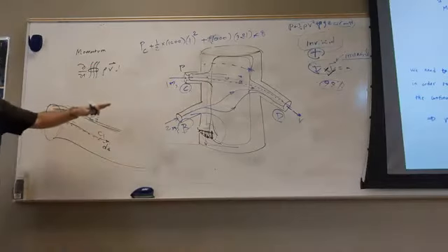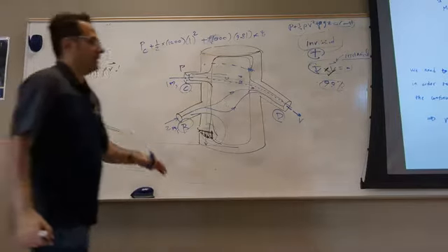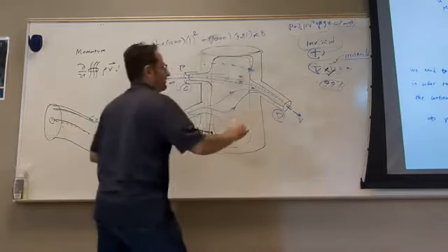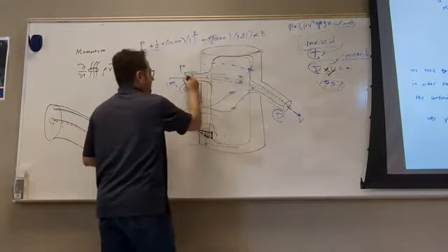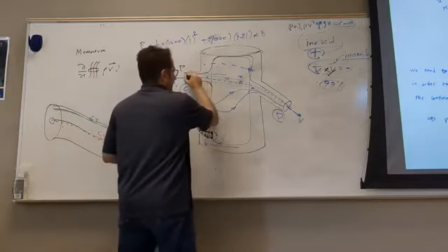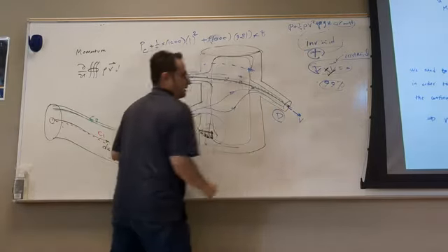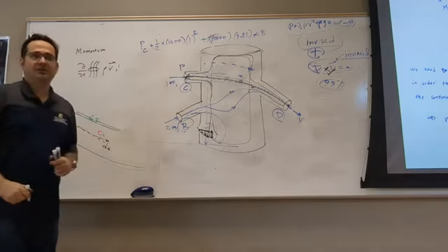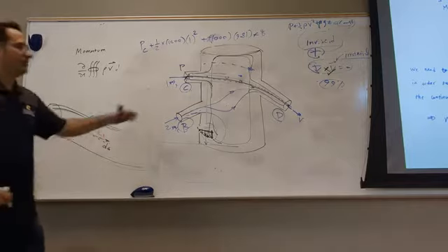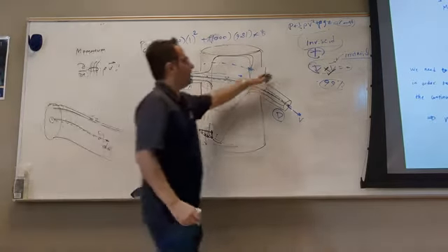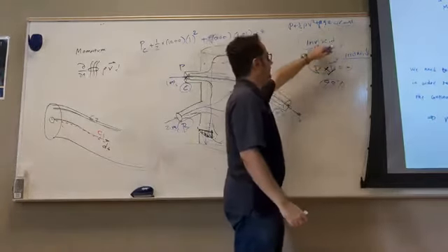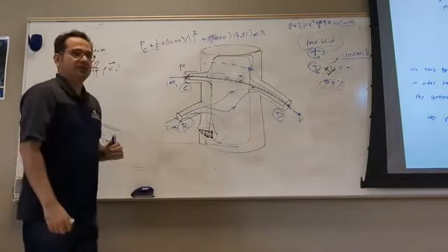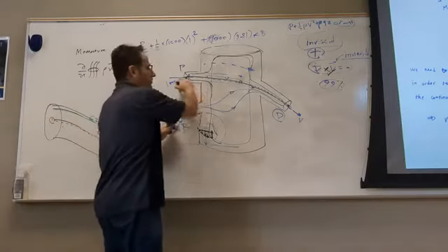And now I want to say why you need this assumption. Let's say I don't make the irrotational assumption. Let's say I only have inviscid. Then I can only write the Bernoulli equation between that point and this one. I cannot write a Bernoulli equation between these 2 points. Why? Because they're on different streamlines. If they're on different streamlines, this constant head is different if you only have inviscid. So you can't write the Bernoulli equation. But if it's irrotational, can you write Bernoulli? Yeah.